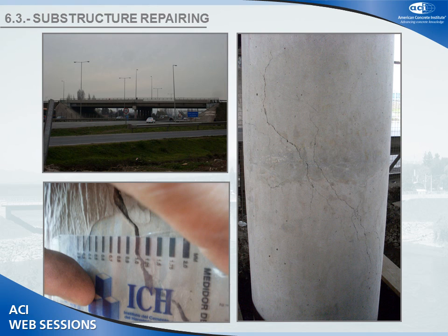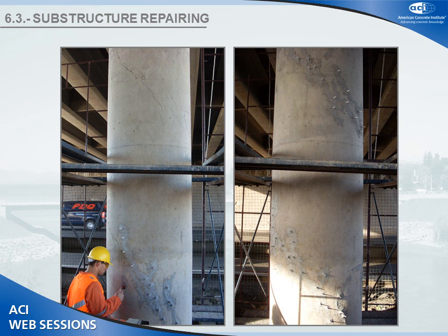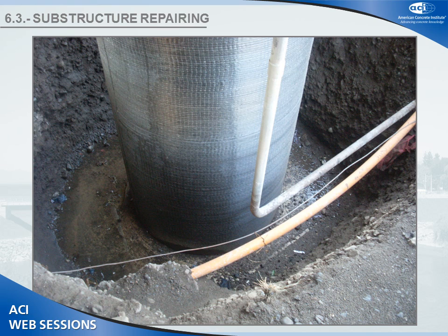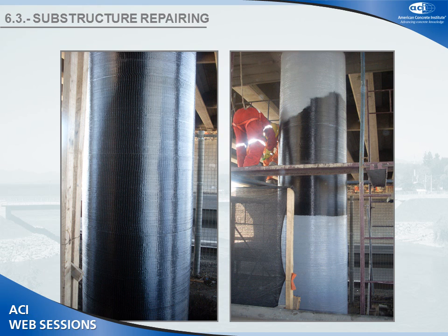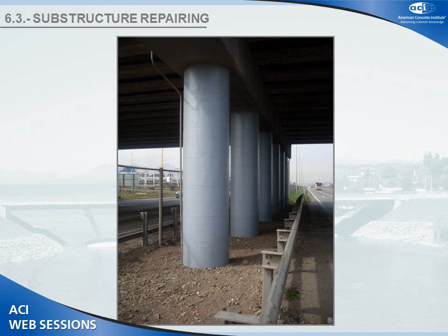This is an overpass very close to Santiago, and central columns suffered some shear cracks because of torsion. So you can see here the injection process and the wrapping with carbon fiber, and the application of protective coat, and this is how that bridge looks right now.